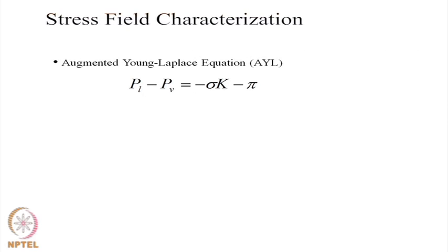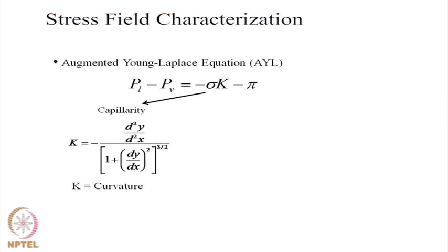So, if you are going to look at the stress field characterization of a thin film, the major governing equation is the augmented Young-Laplace equation. If we just have the Young-Laplace equation, then the second term on the right hand side would not be there.